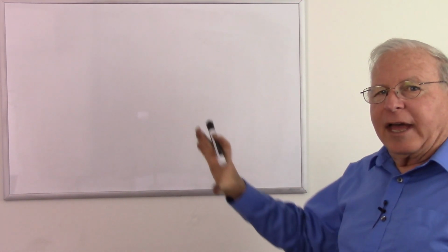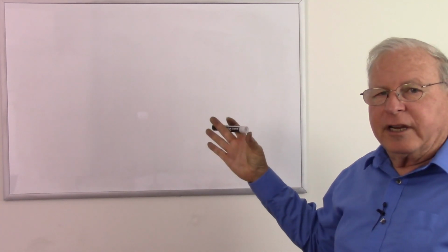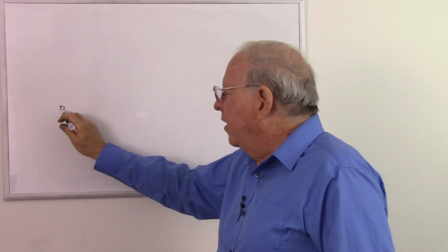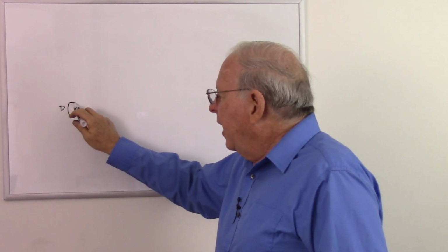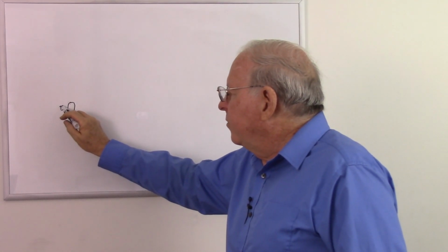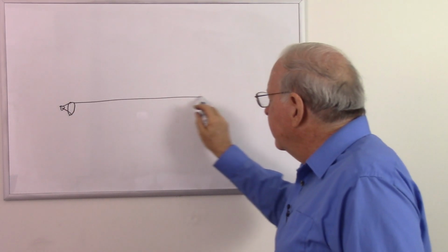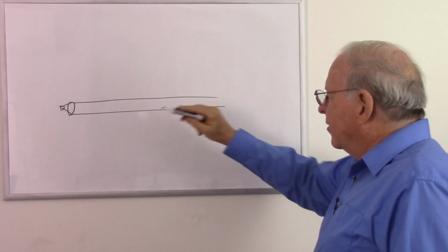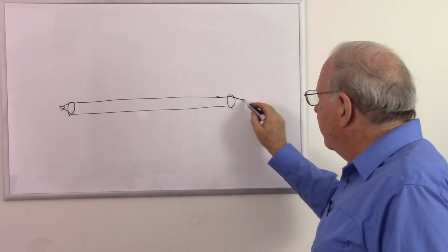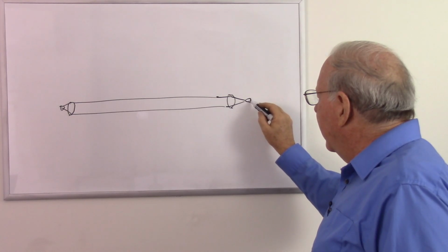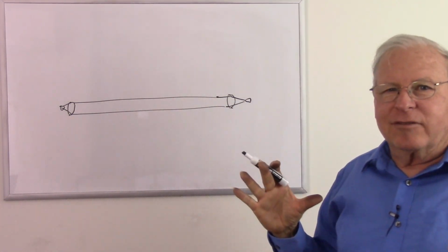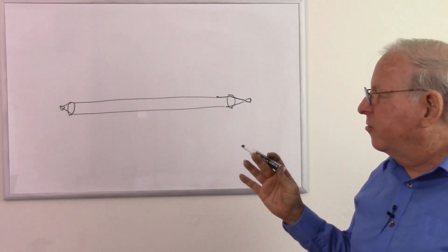So we may have optics that concentrate our light to a point just for detection, and that would be such as like a door opener or something. So we have an LED over here going through a lens, and that's one other thing I need to talk about, what that lens does. That is going to send a column of light across, that's a terrible lens, but I'll try to do a little better here. There's a better lens, and that's going to focus that on a photodiode perhaps, and that's making a beam so that if somebody walks through it, it breaks the beam and detects that something has gotten in there, such as in a garage door opener.